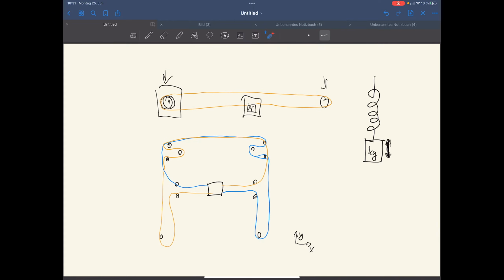So before we now go and have a look at the shaper graphs themselves, I want to talk a little bit about input shaper itself. So now we know how the resonances are measured on the printer with the acceleration sensor. But what actually happens when we apply an input shaper is not that we are countering those frequencies, which is often mistaken for. That's also possible in a control loop, but that's not done in Klipper. What input shaper does is basically avoiding those frequencies.